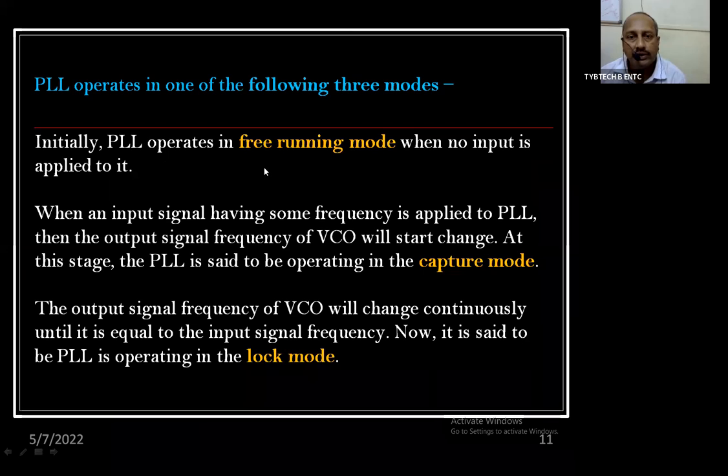So in which mode are they running? Basically, there are 3 modes that we have gone through. The free running mode is when there is no input. When there is an input, it is called the capturing mode, where it is trying to capture and go near to the input signal frequency.